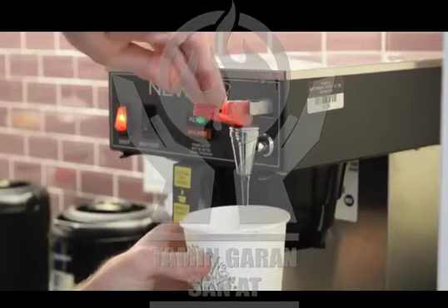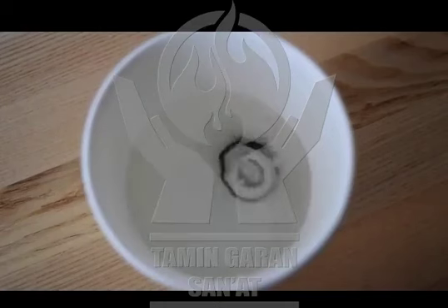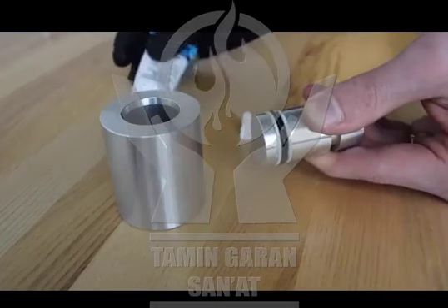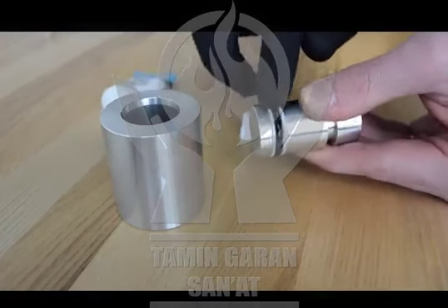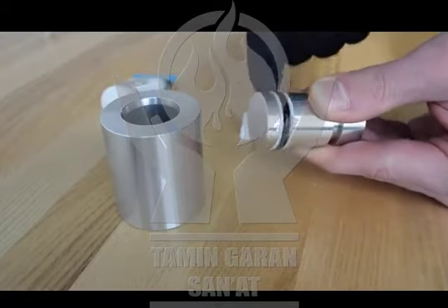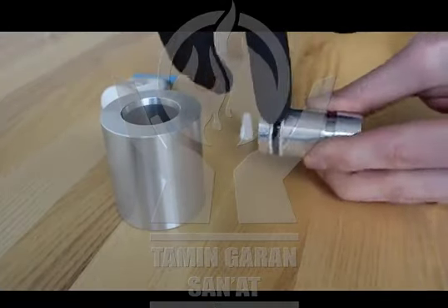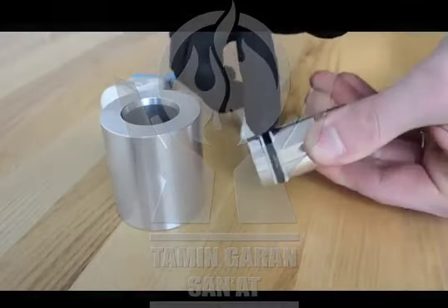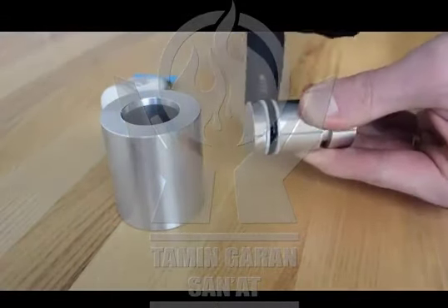A good tip is to drop them in hot water for a few minutes to let them soften. They will be a bit easier to install. Another important installation tip is to apply a high-quality O-ring grease before assembling the parts. In addition to lubricating the rubber and helping it slide easier, most O-ring grease is designed to cause the O-ring to swell slightly, helping increase the squeeze after installation.